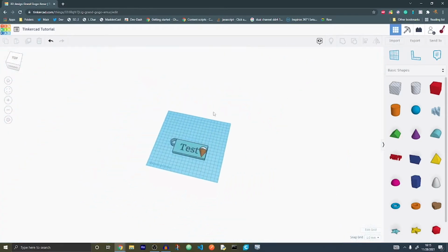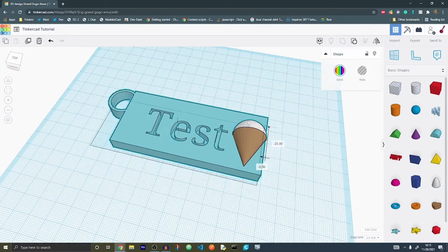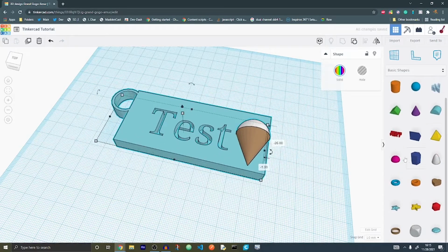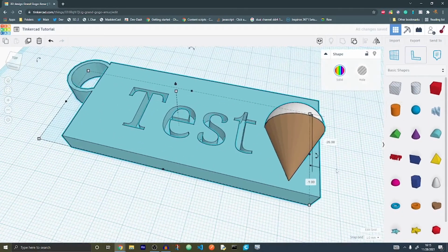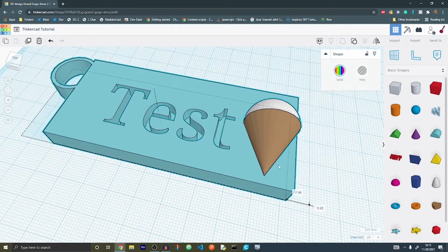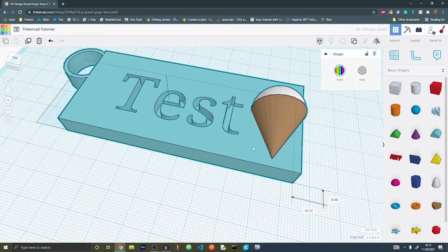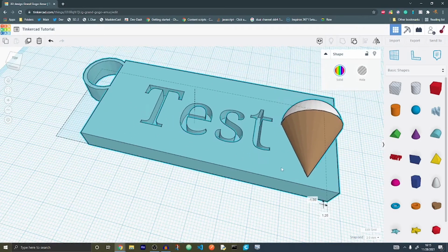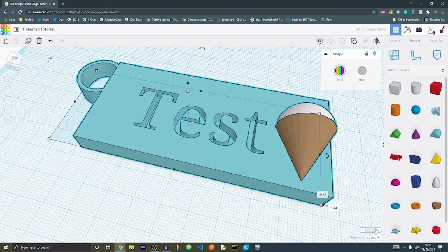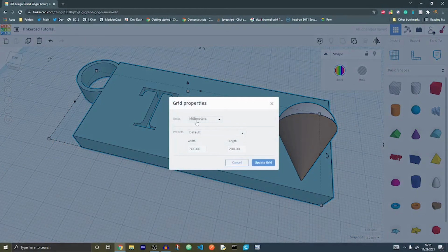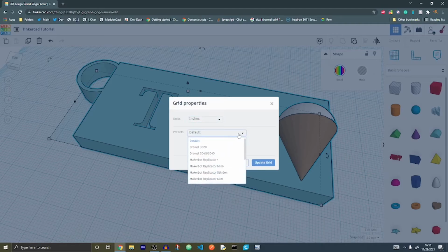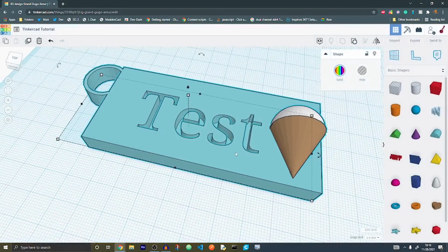Oof. So, yeah, I hope you enjoyed this tutorial, guys, making basic TinkerCAD things. You can mess around, enjoy it, play with it, test anything you want. I'm also going to just say that down here you can turn off snap grid, so the movement will be very smooth. I'd recommend some snap grid, so that it basically makes it clicky, kind of. That's easier for movement and editing, but if you don't want it, you can turn it off. You can also edit the grid and change the measurement type. If you want inches, you can change the size of this, the width and the length.